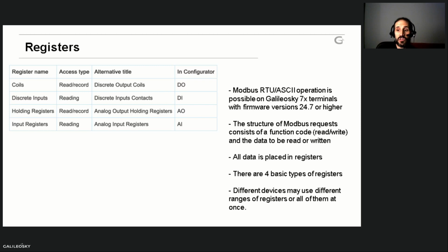This kind of holding register also allows you to write, to send configurations to the slave devices. For example, change the way or the unit in which the data is presented. So you write in this register, and the device will understand that you want to change the way that the device communicates. And also, you have input registers in which you get only data from inputs, right?